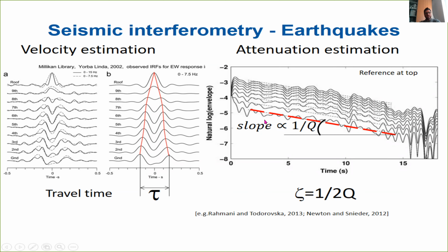A similar operation, again, I want to stress, can be done if you have a borehole where you have an instrument at the surface and many instruments at different depths. You can estimate the velocity of propagation of waves in the borehole, the characteristics, how they are changing over time and depending on the input shaking, so if you have non-linearity, but also, through different methods, you can have some information about the quality factor.